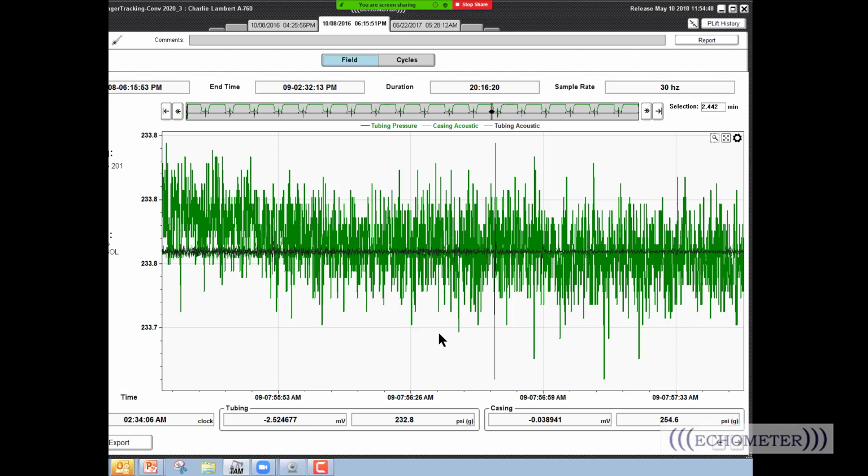On gas-assisted plunger lift, does the compressor need to be off to minimize the noise? Will that matter? That's a good question. The compressor makes noise, and if we're trying to track a plunger and it's being picked up on the tubing, sometimes you may not be able to. It may be too noisy.